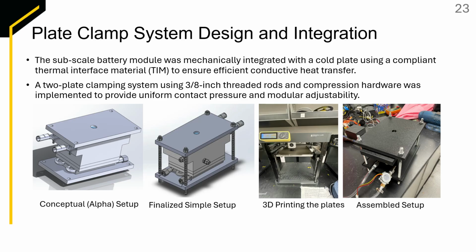For our plate clamp system design and integration, a subscale battery module was mechanically integrated with a cold plate using a compliant thermal interface material, or TIM, to ensure effective conductive heat transfer. A two-plate clamping system using 3/8 inch threaded rod and compression hardware was implemented to provide uniform contact pressure and modular adjustability, as shown in the CADs, as well as the process of printing and the assembled setup shown below.